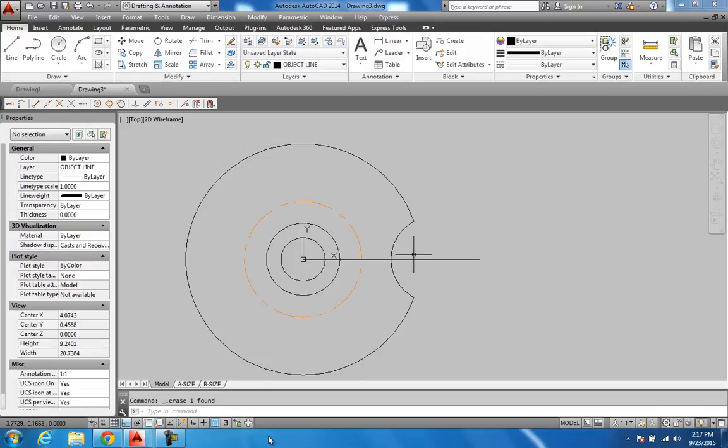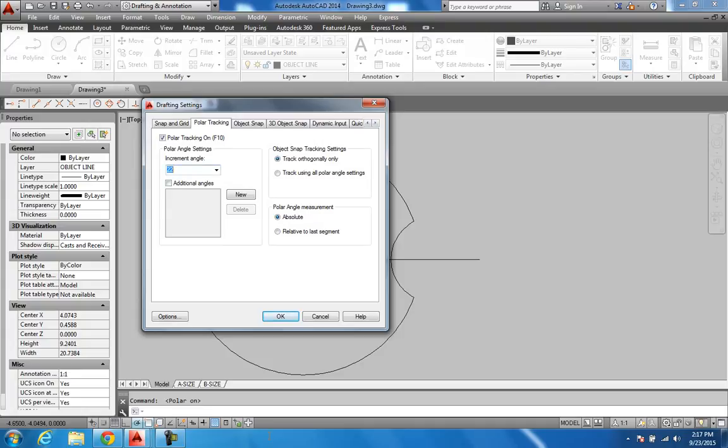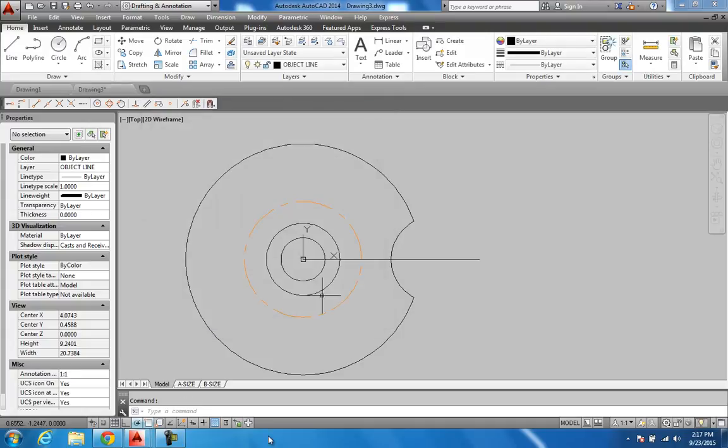So I've got this in, and then it's showing me I've got a 60-degree line coming off the top and down. So if I'm going from 0 here, I'd go up 30. So I would set my polar tracking on 30, or go to settings, and you can change it inside of your settings. We'll change it to 30. Hit OK on that. Now hit myself a line, and I come up 30, and you'll see it'll just like that, kind of perforate itself.